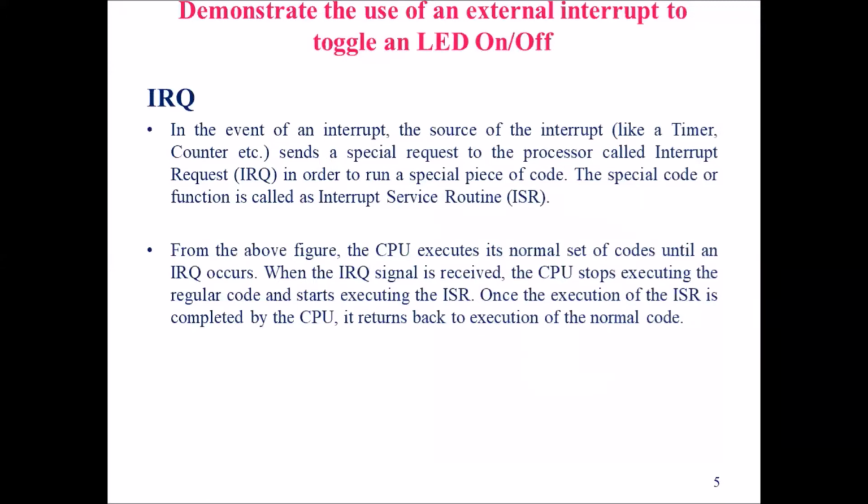Before going into the exact program, first we should know what an interrupt request, or IRQ, is. IRQ stands for interrupt request. In the event of an interrupt, the source of the interrupt, either a timer or a counter, it can be anything, sends a special request to the processor called an interrupt request in order to run a special piece of code. When the interrupt occurs, the interrupt request is sent to the processor to take immediate attention to serve those interrupts.